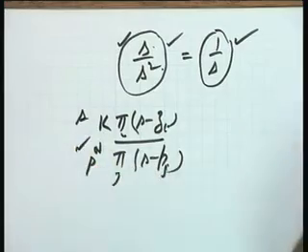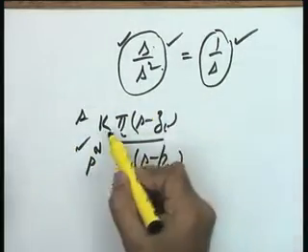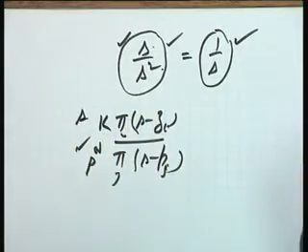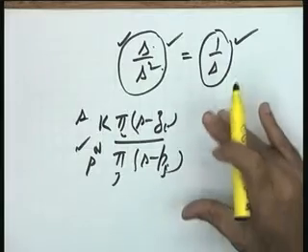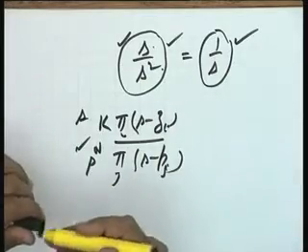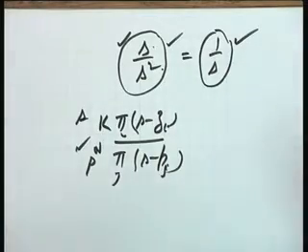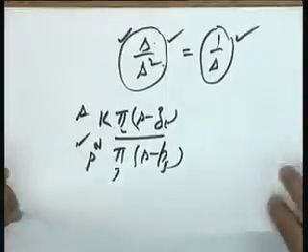When I am defining the type number, I am not assuming that there will be an s in the numerator. I am assuming that this transfer function which you have written has been written after all possible exact pole-zero cancellations, if any, in the model. Okay? I hope this point is well taken. Fine then. If that is okay, let us take the situations one by one.